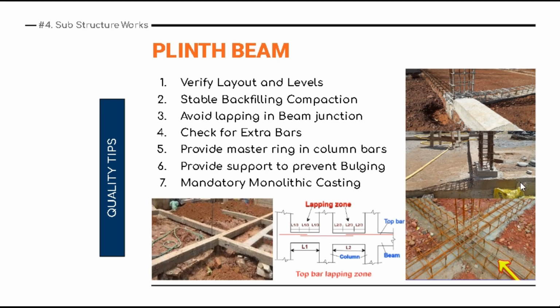Okay, and also see before the plinth beam work, if there is any kind of plumbing related work like underground plumbing, because in ground floor toilets are still there. Nowadays sunken type of toilet is not applicable though, because we have P-trap commodes and sidewise outlets. Still, if there is any request from the client side, then please check it out. All the piping works should be concluded before the plinth beam work.